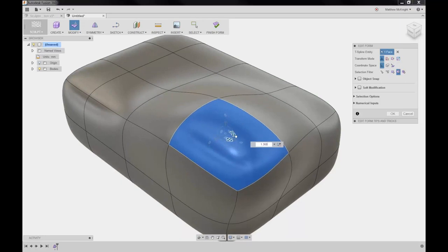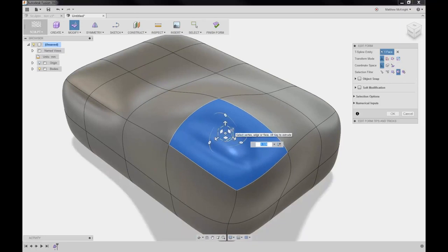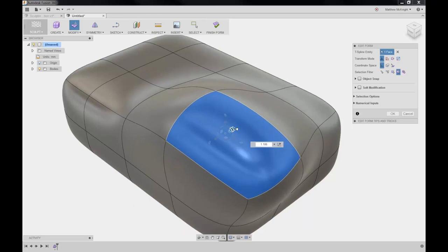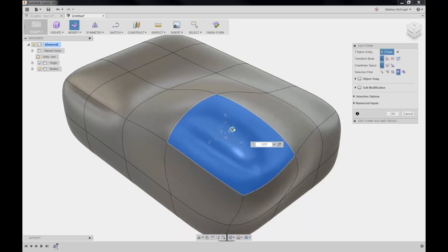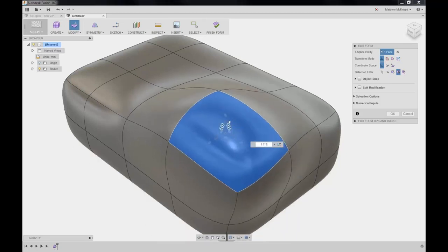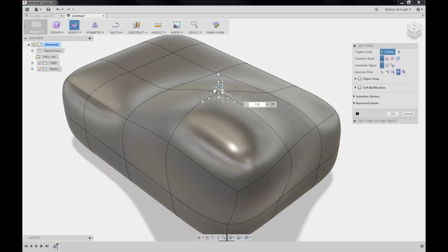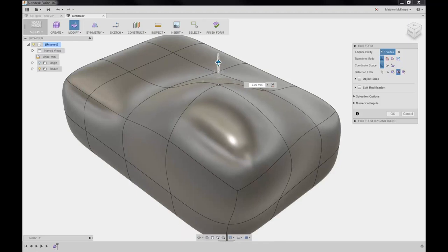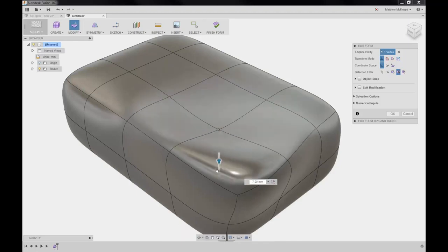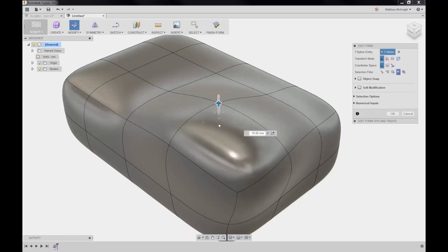So if I wanted to scale the geometry up, I can grab these little line handles that enable me to scale. This is scaled in 1 dimension. If I grab the corner scale and drag that, I can scale it in 2 dimensions. Okay. So we can manipulate our geometry very quickly and very easily. Like I said, if I want to, I can choose not only faces, but I can choose, say, a point or a vertex and move that point in relation or independent of any other point.